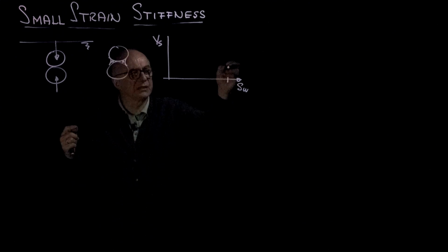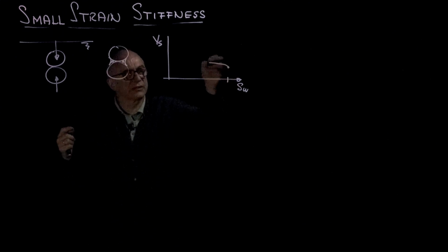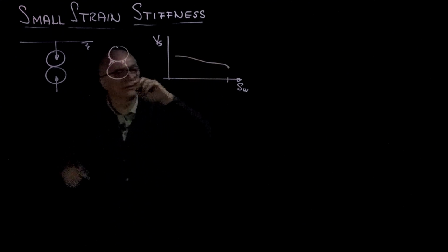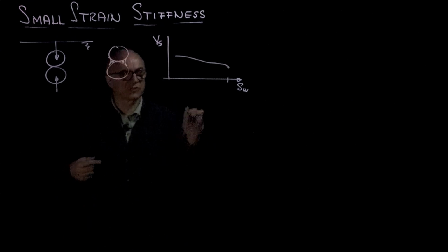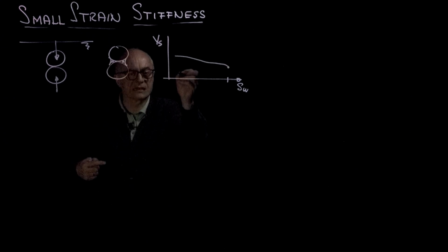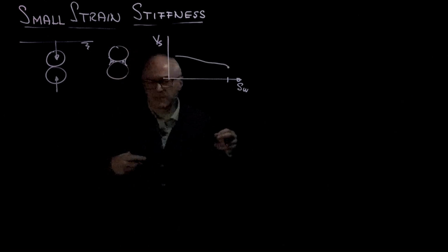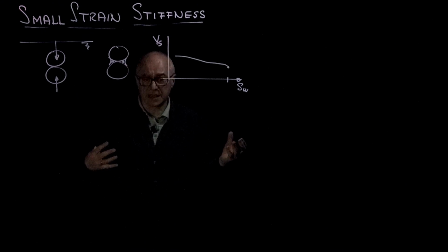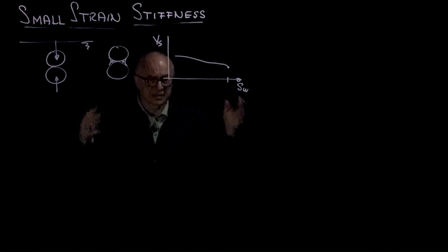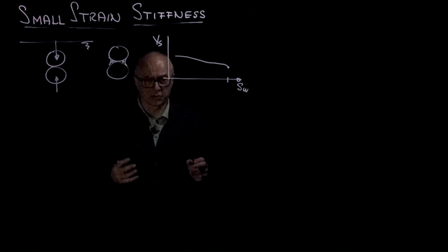However, it's going to begin increasing and increasing until a certain value, which reflects the evolution of suction in the soil. And that increase may be quite significant. In a sand, it may be only another 100 meters per second, but in a silt and in a clay, it could be very pronounced. It can bring us to 700 meters per second or more.